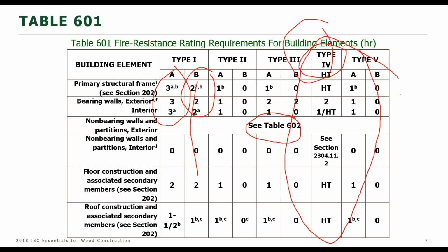Let's say the sprinklers don't work and the fire department does not arrive. The goal of the protection provided in the 2021 code is that a content fire can burn out without potential for any structural collapse in that building. That's the assumption pretty much for type 1 now. That will be the assumption for type 4A when it's in the code.